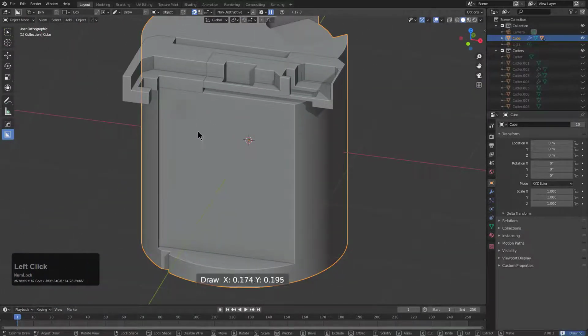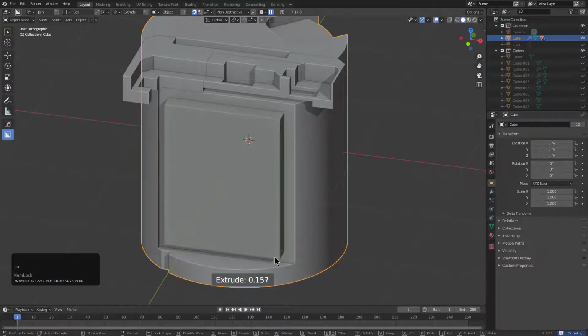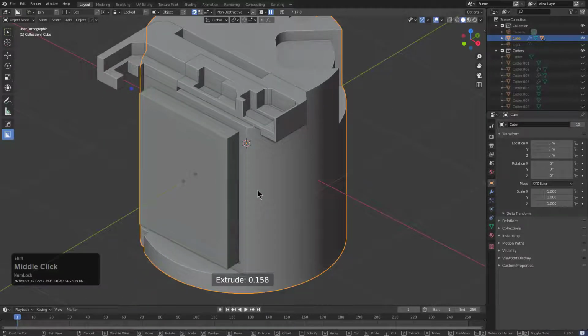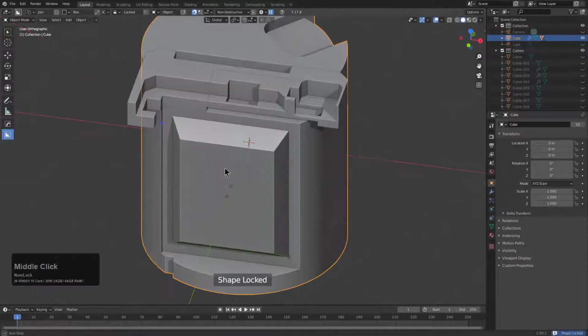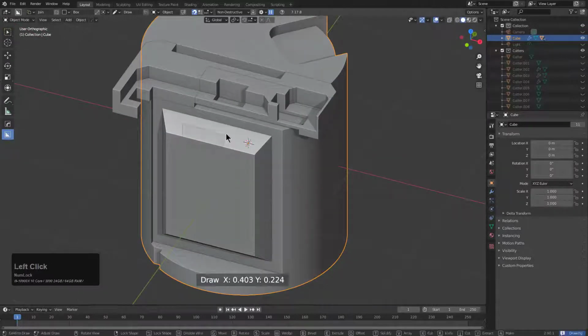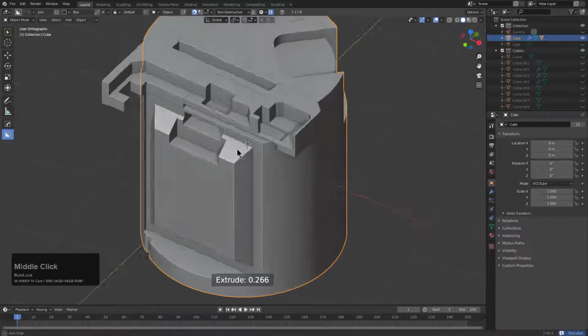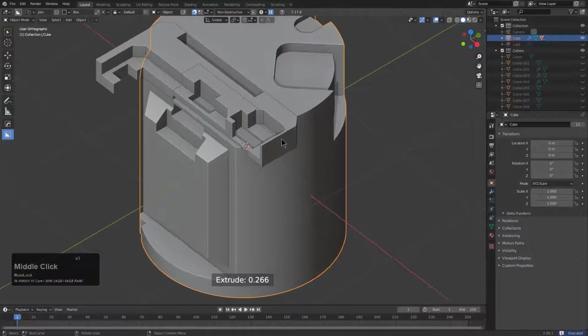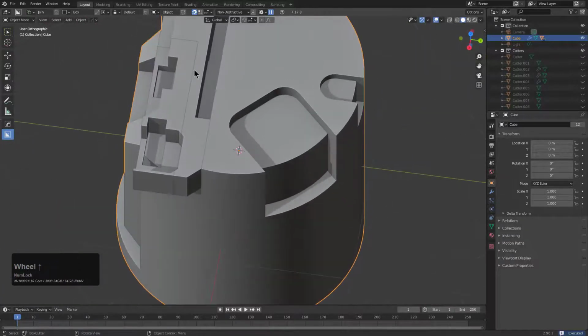So whenever it comes to drawing a shape and actually having it unify with the original shape, that is where join comes in. I just drew a shape, press Shift T in order to taper, and now this shape is now part of the initial shape. Sometimes I will press J in order to jump over to join, but normally I never start with join as an actual start state. Seeing a green box on screen is quite interesting to see, something I normally never see.